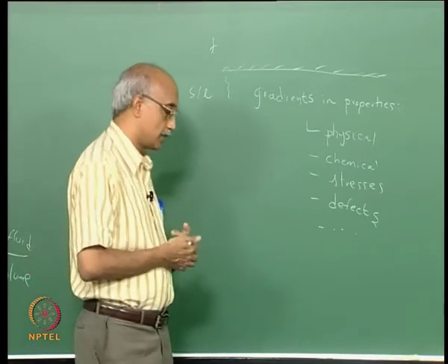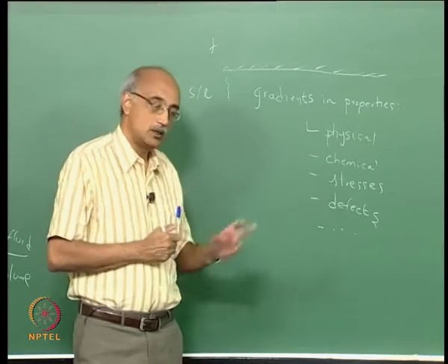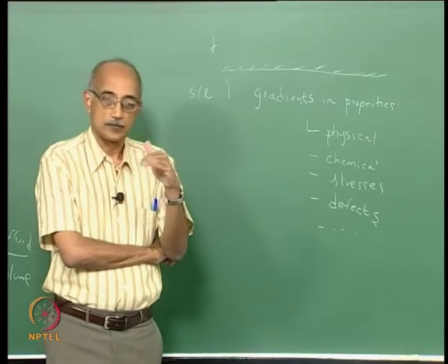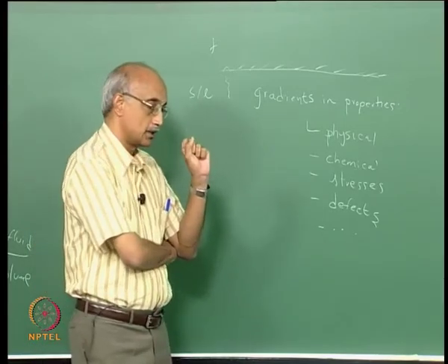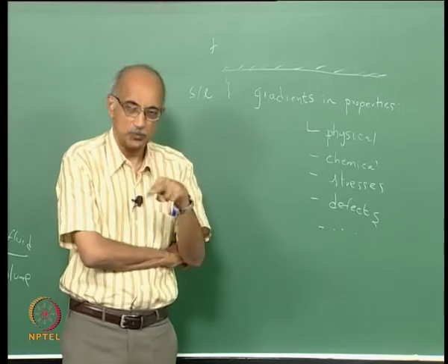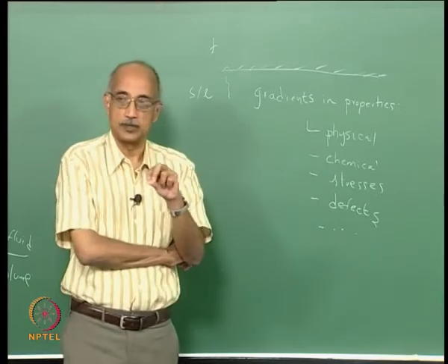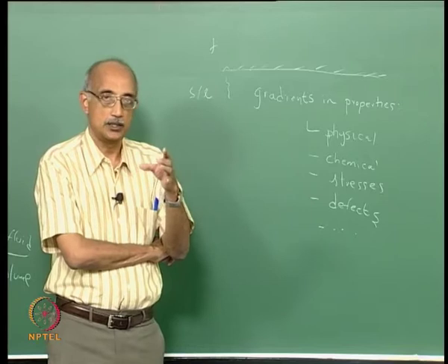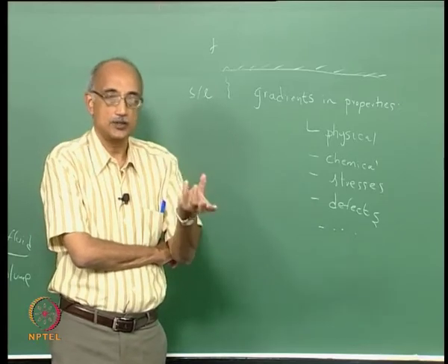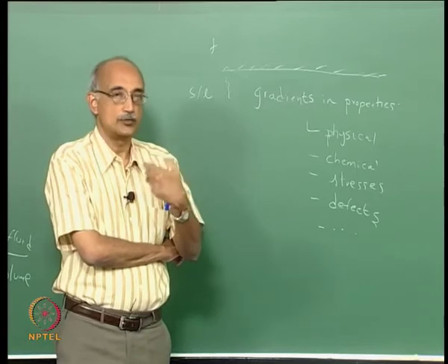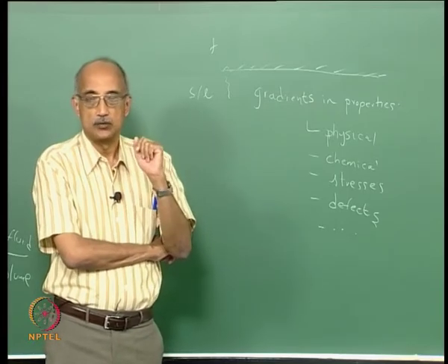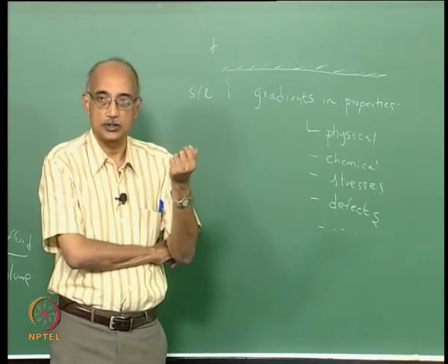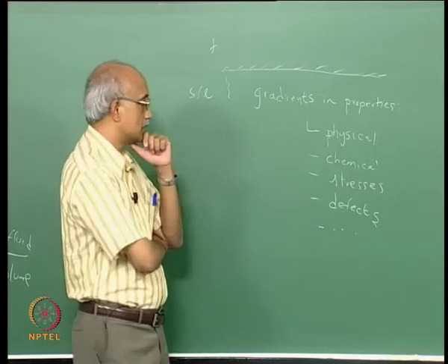Now, that is an example of again a chemical or compositional gradient which will then exist from the surface to the subsurface. And the reason for that is that the process by which you are introducing the carbon into the metal, into the alloy, is through a diffusion process. So, typically you would take a carbon containing species and let it diffuse into the metal. For example, it could be something as simple as carbon dioxide, or it could be some organic carbon like methane and so on.